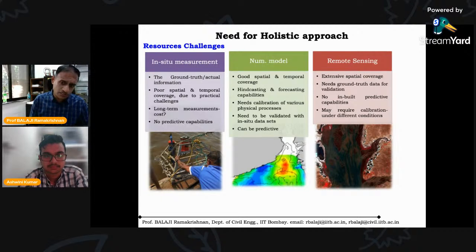The advantage of using such satellite imagery is that, being in the sky, they are able to cover a large spatial domain. In one single snapshot you can probably cover nearly a quarter of the entire Indian subcontinent, if really required. But since they still require some kind of algorithm to extract the engineering parameters, we need some ground truth data from actual field measurements. It can be limited as well. Then use this to make sure that your predictive algorithms are actually working well.